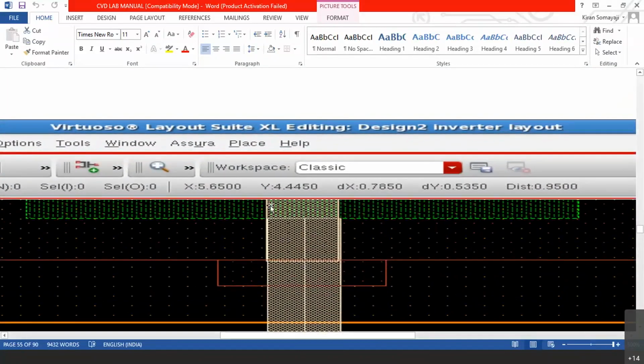Now you can see, right? The PMOS gate is here, whereas the poly path is slightly offset. This is an overlap error. When you perform the testing of this layout, the tool will give you an error message, because this is not advised. Remember, we are dealing with nanometer dimensions, so it should be correctly overlapping there. Below polysilicon, we have oxide by default, right? Now, oxide and poly will not have a correct overlap at this particular area. That will lead to an error.